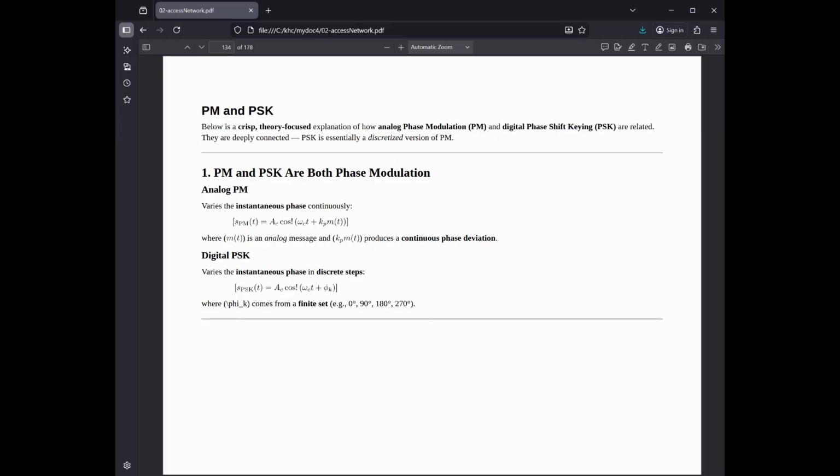The math: a PM signal is generally represented using carrier amplitude, carrier frequency, phase sensitivity, and the message signal, data. Key characteristics: constant amplitude. The signal strength doesn't change, making it very resistant to noise, which usually affects amplitude. Relationship with FM: PM is mathematically related to frequency modulation, FM. In fact, changing the phase rapidly also changes the frequency, which is why they are both called angle modulation.